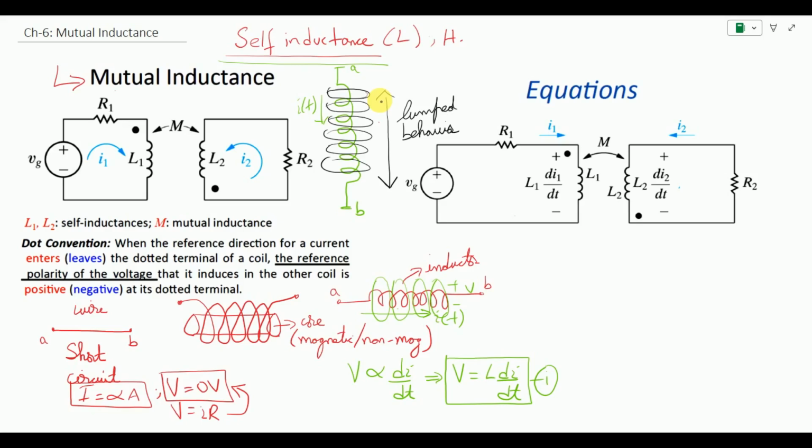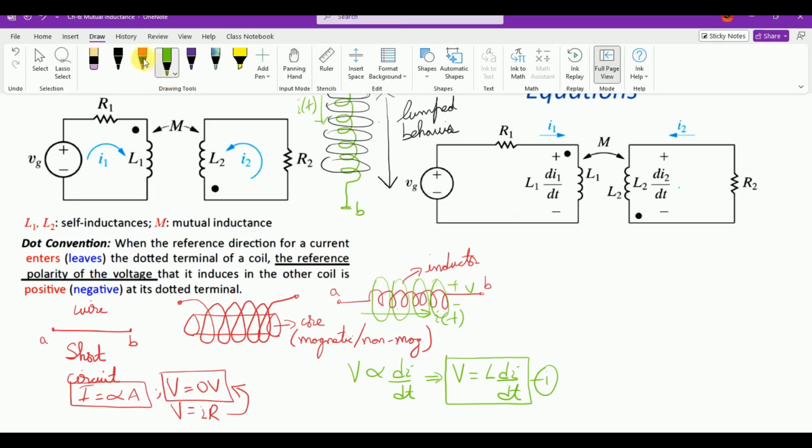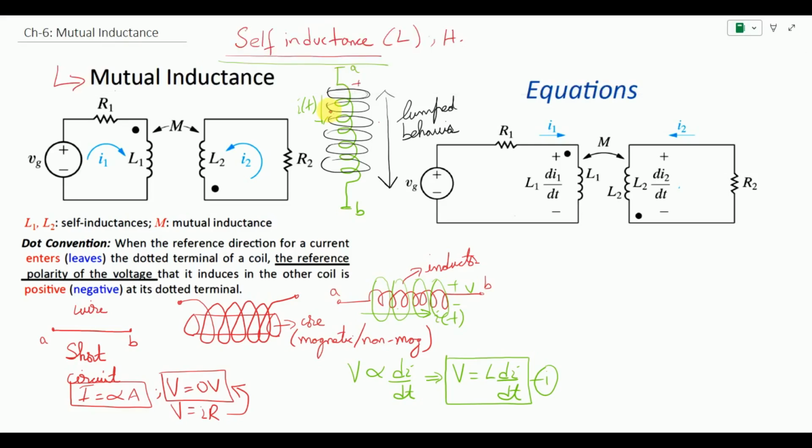But if you look back into each segment, Faraday also proposed that each magnetic field in this segment is producing an induced voltage on it. This portion will have an induced voltage of V, then this coil will have another induced voltage, this will have another, and so on. This process where the flow of current produces a magnetic field and the same magnetic field produces an induced voltage in the single inductor is known as self-inductance.